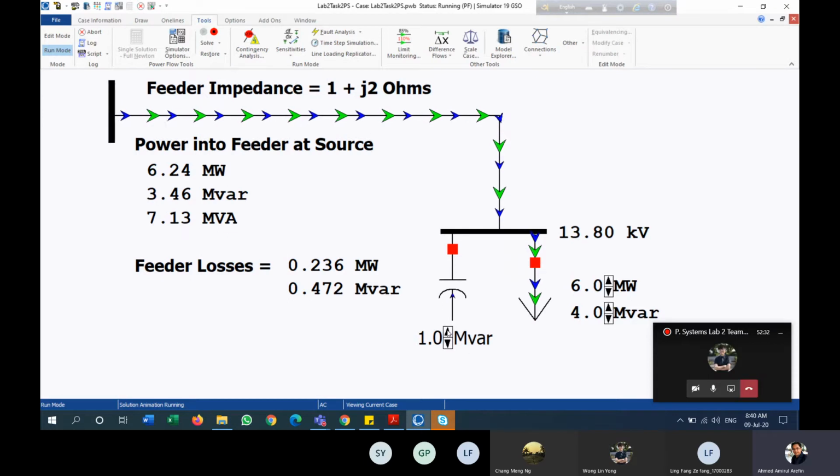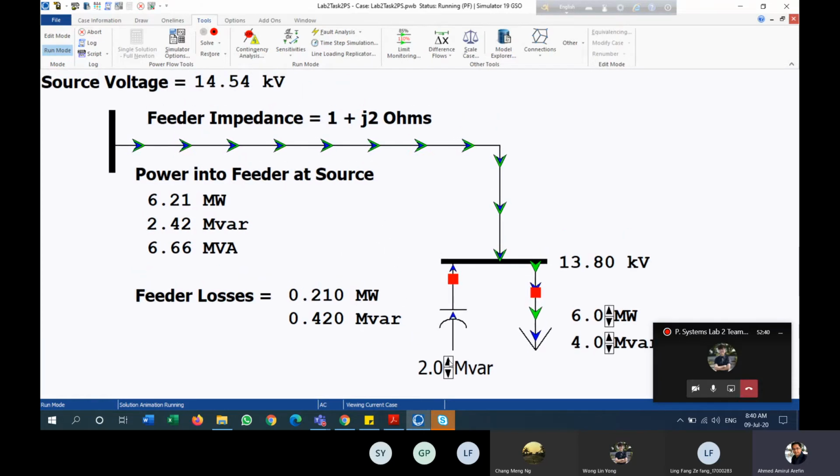So the theory is that the capacitor is basically supplying reactive power, and once you change the value of the capacitor in the positive direction, it is also decreasing the source voltage, because it is supplying the reactive power. So we are interested in changing the value of the capacitor or the inductor. We are not interested in changing the value of the load. But we do need the load, because from transmission sending end to receiving end, we are feeding this load.